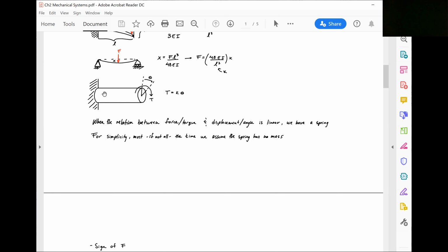If it is really rigid, you can make it big enough to be really rigid for that load, but it is not wise engineering, and that's not why they pay you, because they want to get away with as little, as cheap as possible, and do the same job. You can make it more rigid with a thicker or larger beam, but you don't want to do that because you can model it and do it with smaller ones. A safety factor of 100 is not acceptable for an engineering project.